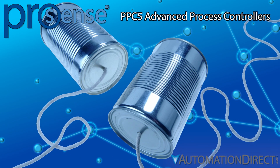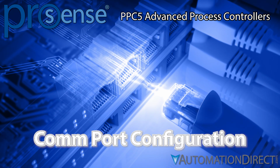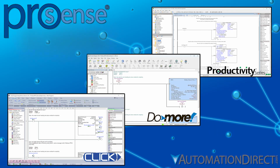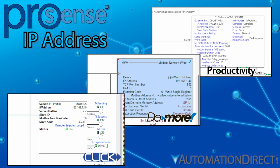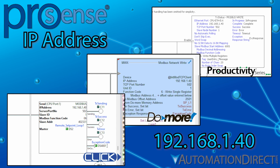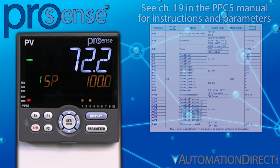Before we get to any communication, the PPC5 will need to have its COM port configured to put it in the same subnet as the PLC. All of the example PLC programs will attempt communication with the IP address 192.168.1.40. So that's what we'll program into the PPC5, and we'll set that up through the controller's face.